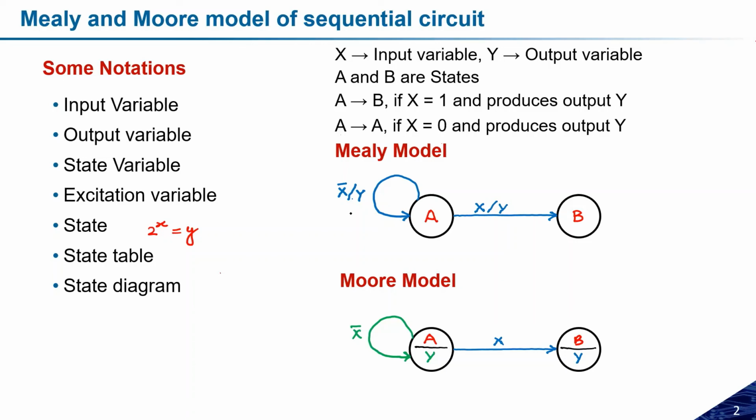Okay, so the next and important, the last parameter that I have to consider is the transition table. What is this transition table? The state diagram and the state table represent the states using symbols or names. The transition table is a kind of state table where states are represented by actual binary values. Here A and B are some symbols which we use to represent states in the state table and state diagram.